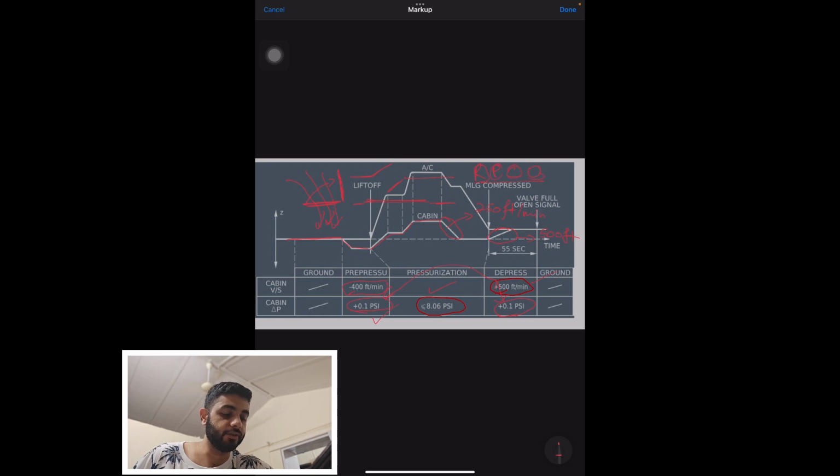Okay, residual pressure control unit. Now what happens is sometimes pilots forget that we have kept it in manual mode. We have landed the aircraft and the outflow valve was in manual mode. Maybe a CPC failure, maybe you have manually kept it in that mode, maybe the outflow valve is not opening on its own, some problem is there with the signal going to it.